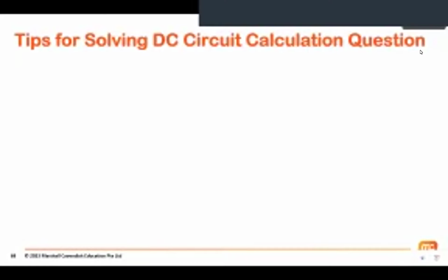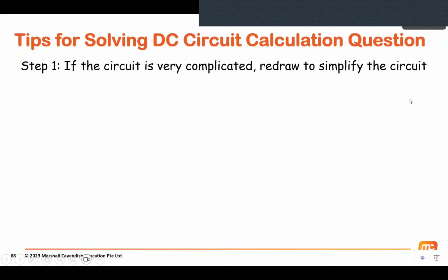For solving DC circuit calculation questions, these are some of the tips that you can use when you come across a circuit diagram and you do not know how to start. Okay, so the first step, if the circuit is very complicated, you have resistors all over the place, is always to redraw the entire circuit to simplify it.